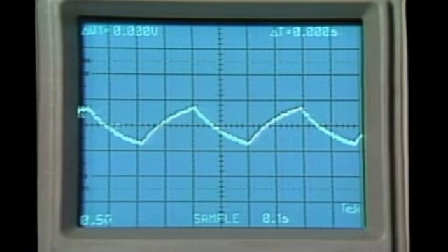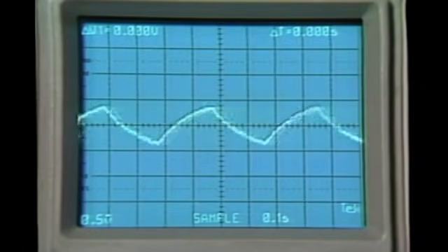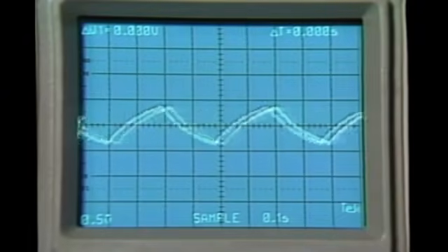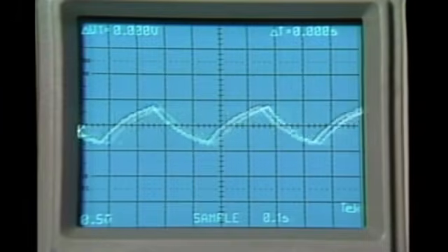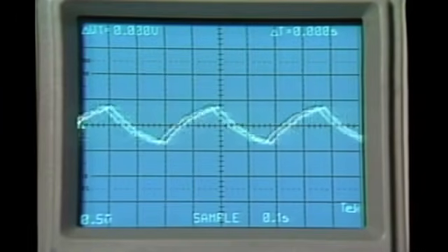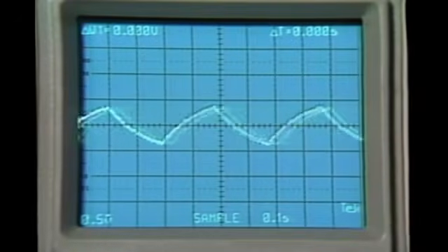Scan is the normal display mode associated with digital scopes. A trigger is received and the scope displays a trace from left to right. Another display format is similar to an electronic chart recorder. This method, known as roll mode, usually is used on slower sweep speeds. This mode disables triggers, so signal data is continuously acquired and displayed. The waveform display scrolls from right to left across the CRT with the latest samples appearing at the right edge of the CRT.